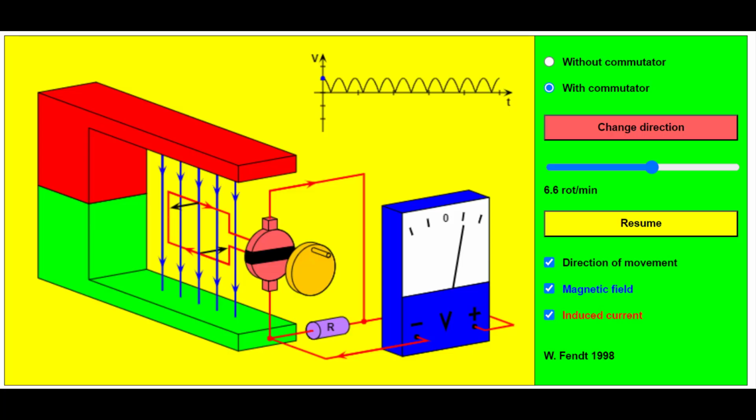Okay, now let's look at this very nice simulation for a direct current generator. Just as we spoke before, it looks exactly like a motor where we will have two brushes and there's this small gap which is colored in black. Let's start this simulation. As we can see, there's this lever arm which is rotating this loop of wire. When this loop of wire is rotating, as you can see, the number of magnetic lines passing through the loop is changing, which is exactly changing flux. Since flux is changing, we are producing electricity.